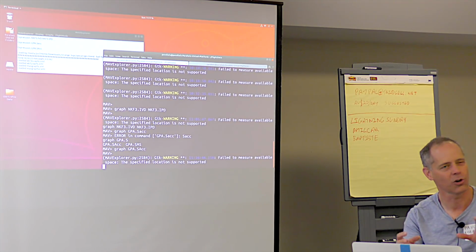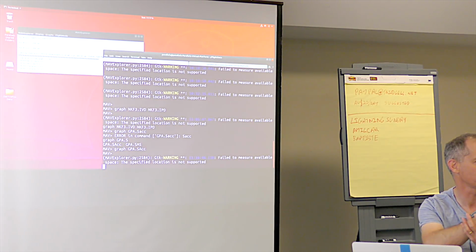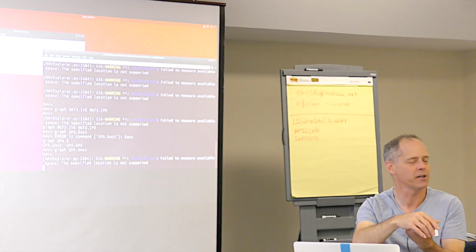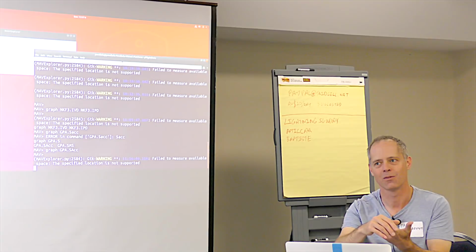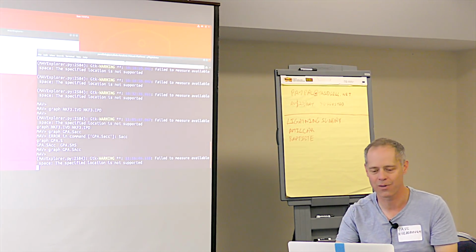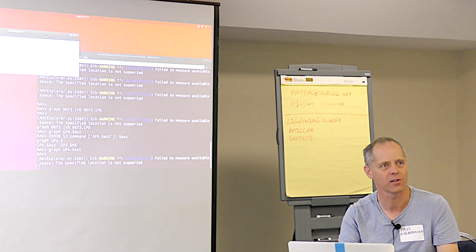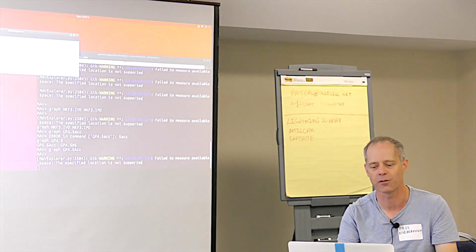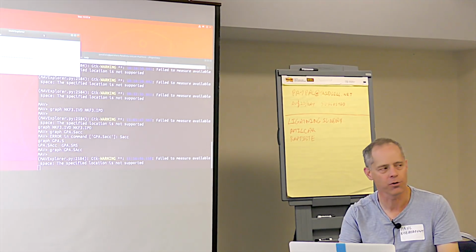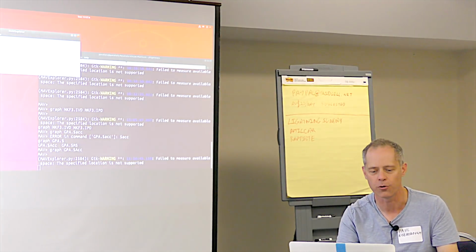The EKF can tolerate one error, but sometimes you see a log where the magnetometer hasn't been calibrated correctly, or it's got interference. The GPS is noisy and been interfered with, and there's high vibration. You put all of those together, and it may work on ground testing. It gets into flight, and then 15 seconds later, it's all over. So we have progressively improved the way that the user is notified of these errors, but there are still some areas that we can improve.